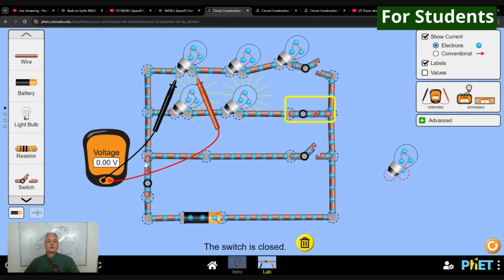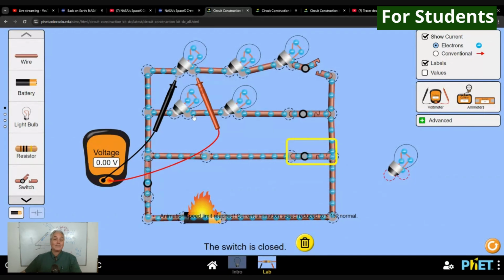So here we have the electrons that are going to those 2 bulbs. What would happen if I close the switch here? So here the electrons have a choice to go on this line or to this one here where they're slowed down by the fact that they have to give energy to the bulb. Having a choice between going through the bulbs where they're slowed down, they would actually go through the wire that has no resistors. Consequence, the electrons go here, get energy, go around, more energy, and then your battery is causing an issue. And that is a problem right there.